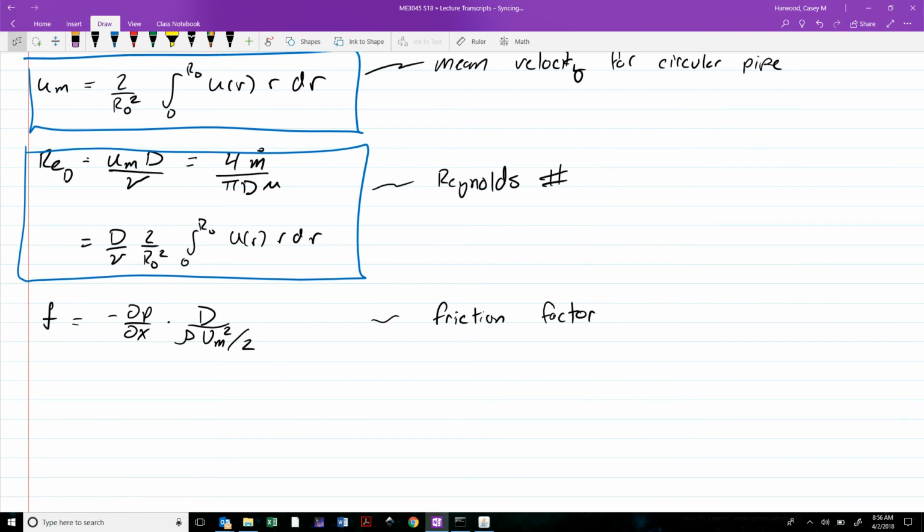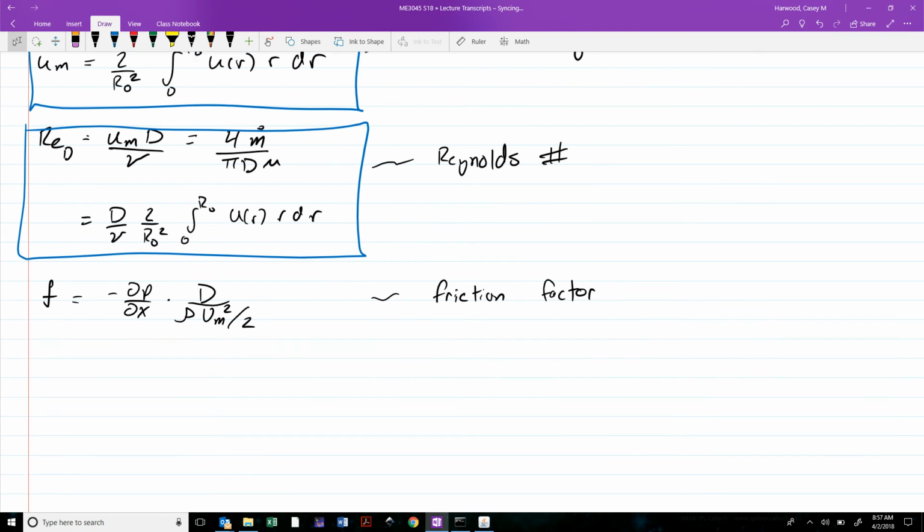And so from this pressure drop, if you know the friction factor, and you know the length of the pipe as well as its geometry and the mean flow rate, then you can figure out how much lower the pressure is going to be at the downstream end than the upstream end. Therefore you can figure out what kind of pressure boost a given pump needs to provide in order to drive the flow with those given conditions, and from that, the pump power. This is relevant to heat transfer, because this has a lot to do with things like flow through heat exchanger tubes. It comes down, at the end, to how big of a pump you need in a lot of cases.